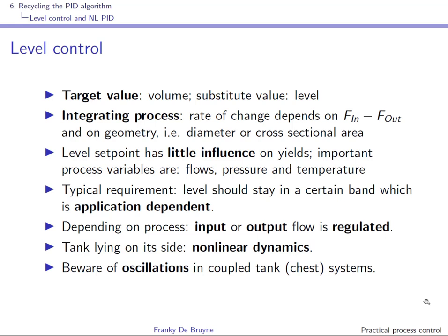Of course, if this cross section is not constant, and this is for instance the case when the tank is lying on its side, or you have a conical tank, then the dynamics become non-linear. We have seen this when we have talked about integrating processes, and indeed the dynamics between the difference between the input and output flows to the level is that of an integrating process, and the relation is linear, as I said, if this cross section is constant.